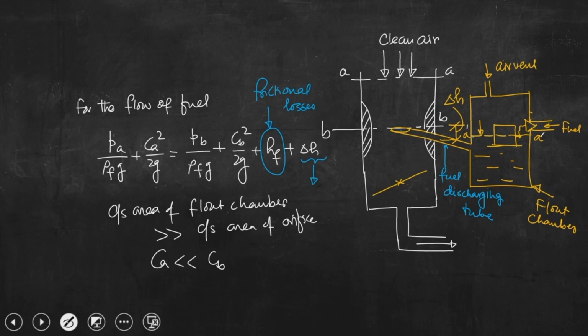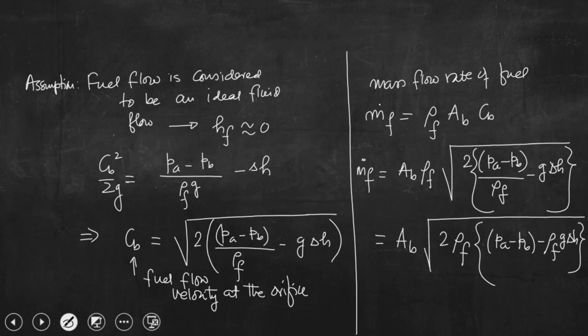We have also ignored the frictional losses, that is both internal and external frictions, and surface tension force we did not consider. Accounting for these factors, the expression that we have established here is not the actual mass flow rate of fuel that we are going to get, right.